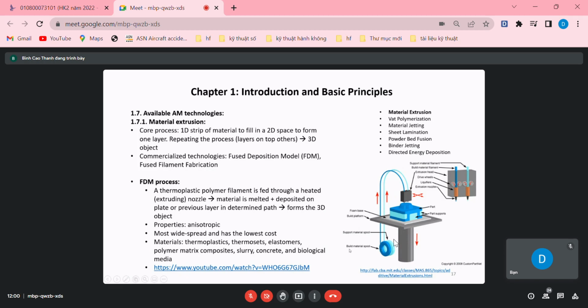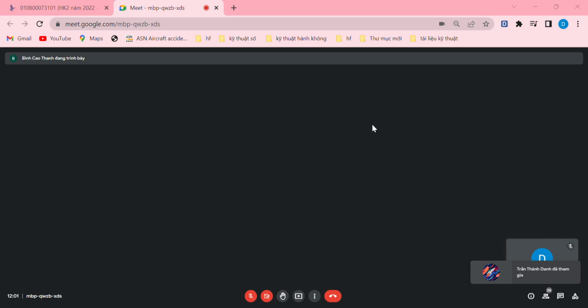So both the building materials and the support materials. So they are two separate things. Basically, the support material is cheaper than the building material for sure, because afterward we need to eliminate the support structures and to recycle the support structure material.